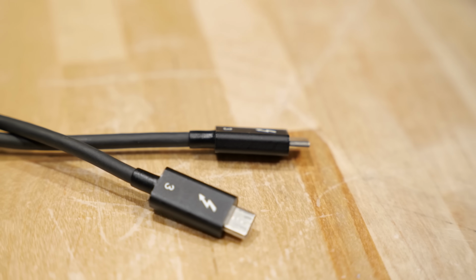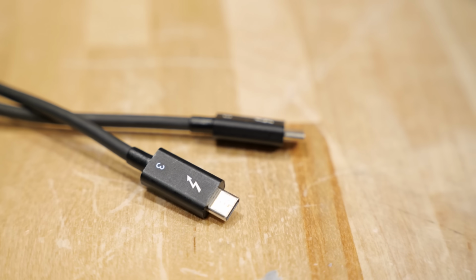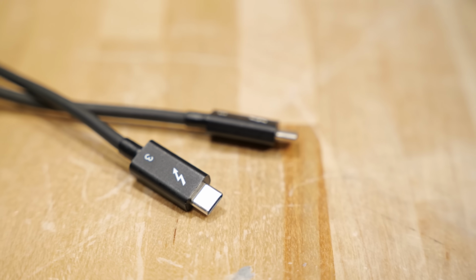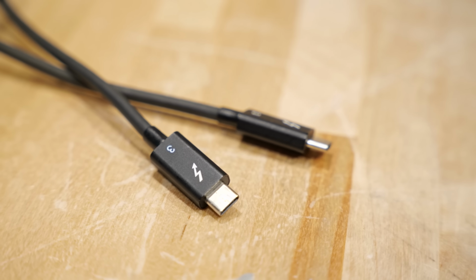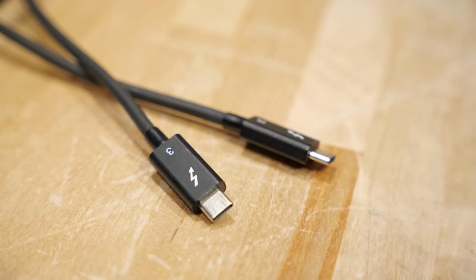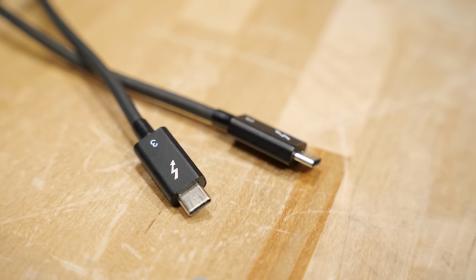There are some things where it legit is just one connection and it can electrically route it between the top and the bottom half of the connector. But at least for the 2x10 gigabit connections, it really is two 10 gigabit USB connections. By the same token, Thunderbolt, the original Thunderbolt 3 specification, actually allowed up to 8 PCIe lanes in this wire, which is wild. The reason that you don't see that very much is it is very difficult to get certification.